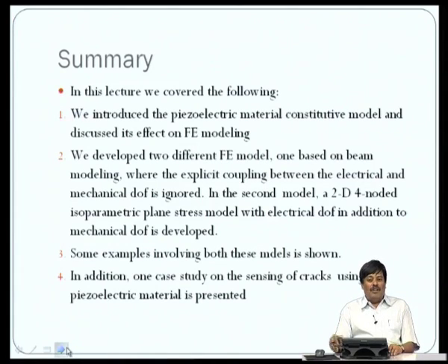In the second model, we developed a 2D 4-noded isoparametric plane stress model with an additional degree of freedom in the form of the electrical field. And we again studied the same actuation problem, that is, giving a voltage and trying to reduce the total deflection in the beam structure.